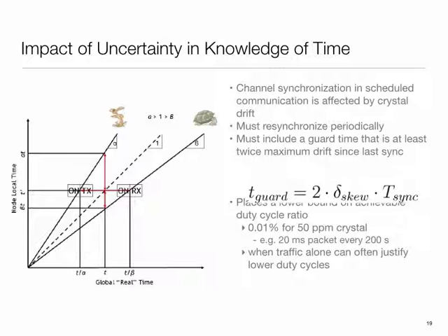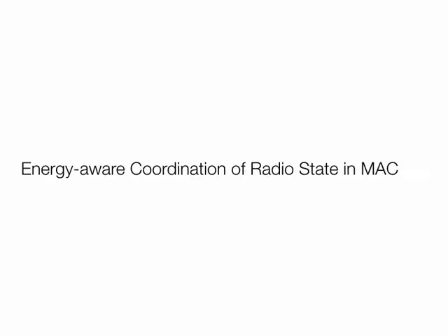And if you calculate the numbers and the amount of drift that will happen and all, it's just not possible unless you put atomic clocks down there, but then you are increasing the sleep mode power. So these are applications where a very low duty cycle was possible from an application perspective, but it's prevented by clocks from happening. So duty cycling is one friend, and playing with the preamble or playing with packet trains is kind of an idea.